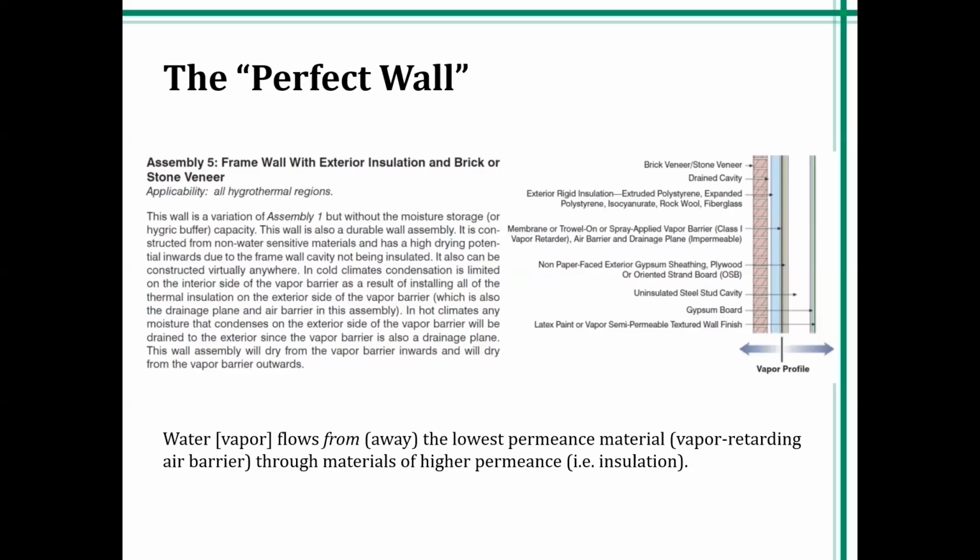Something I think has recently changed with the position of these manufacturers of XPS, at least I think in the case of the blue stuff, I can't use product names here, but these manufacturers are moving towards the recommendation of not taping. Yes, they are. The rigid insulation manufacturers are moving away from requiring the taping of joints of the insulation.